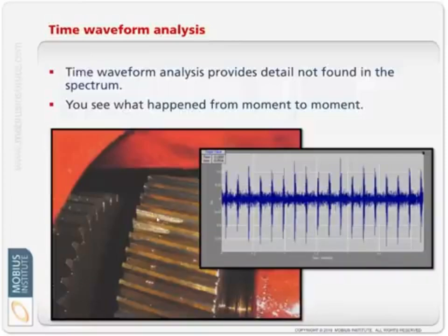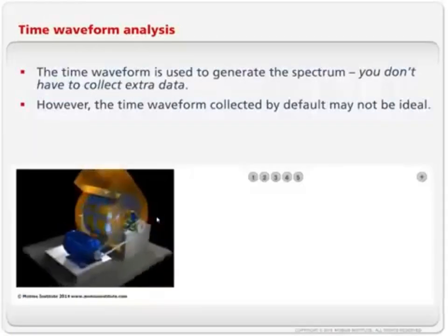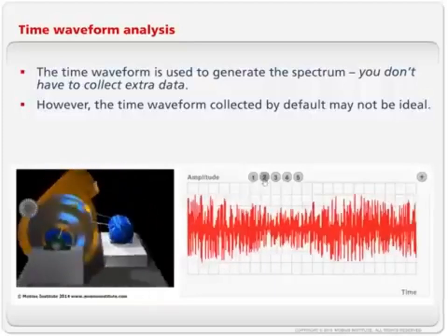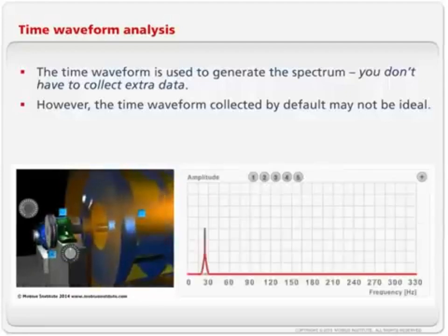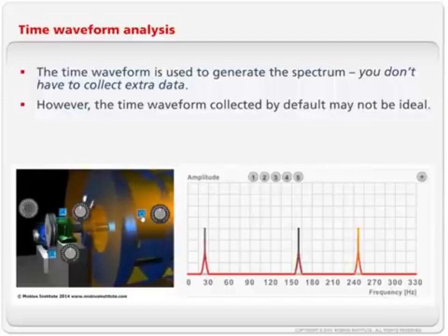So I can look at this, I can look at the G's level, the peak acceleration level, and I can detect the severity of the problem, and I can see things that are very hard to see from a spectrum alone. So time waveform analysis really complements the spectrum analysis, and vibration analysts that are masters of their domains, so to speak, I would like to think they would use this time waveform analysis. And it's just the same thing we saw before. It's just taking that vibration, but rather than breaking it down and just looking at the spectrum, we can look at the raw waveform all by itself.